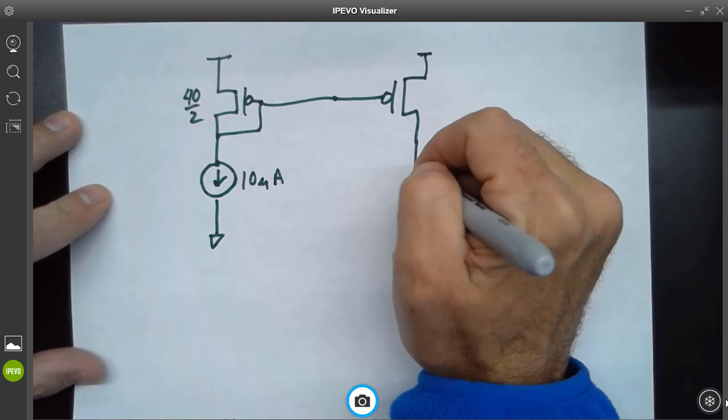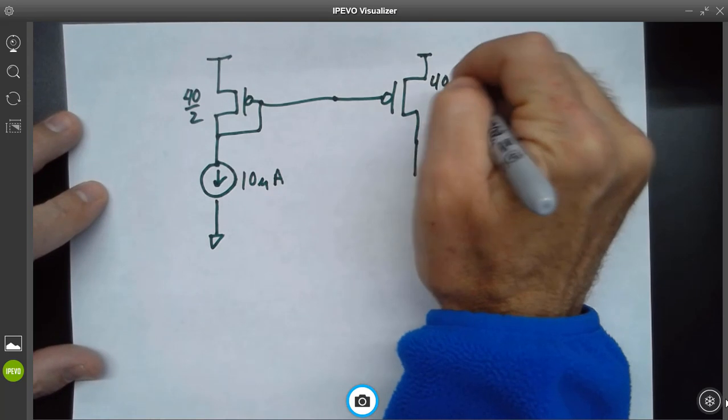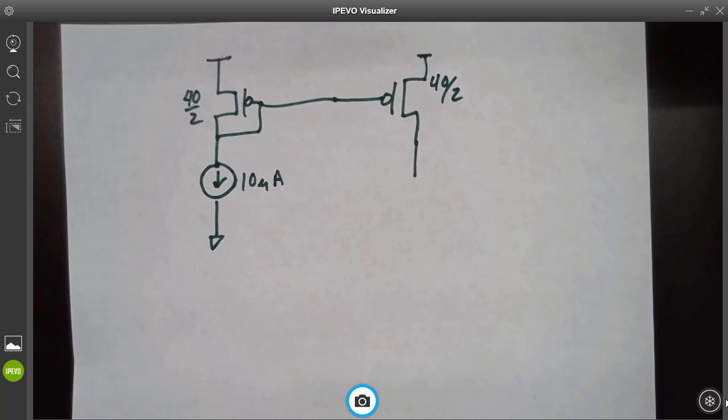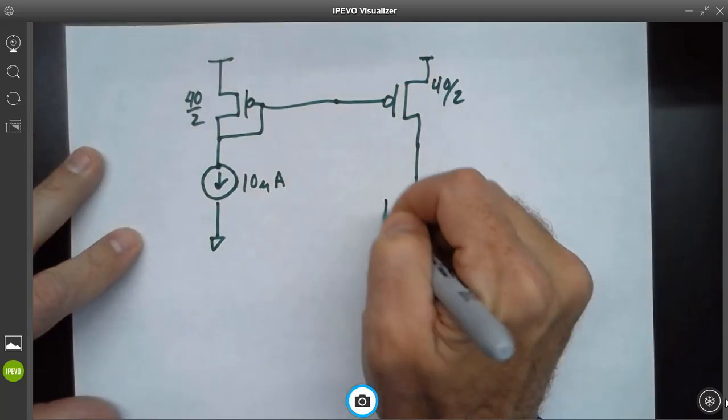And what was the typical output resistance for one of the MOSFETs with the long channel process? 5 meg? All right, so we're going to make them have a resistance of, how about a gig? Make it much bigger.